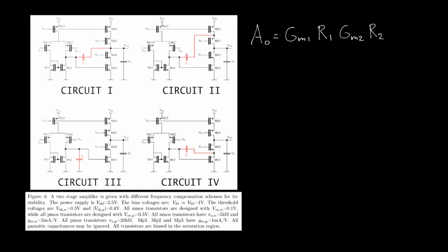second stage. The transconductance gain of the first stage is quite simple to find if we look good at the figure. The small signal is imposed on this terminal here, and that is a PMOS transistor. So that means that we will have a transconductance gain of GmP. The output resistance of the first stage can be found if we apply some simple small signal analysis to this differential amplifier. As a result, the output resistance will be equivalent to the resistance of this PMOS transistor in parallel with the resistance of this NMOS transistor. So that is RoN in parallel with RoP.